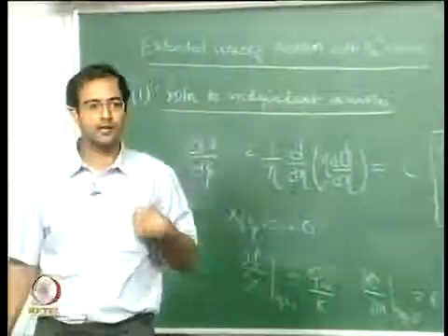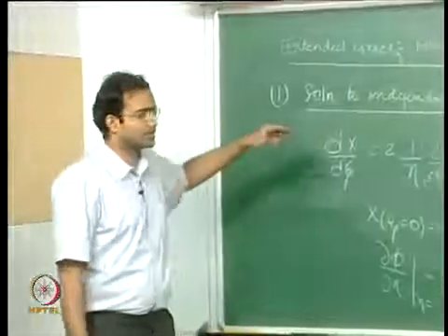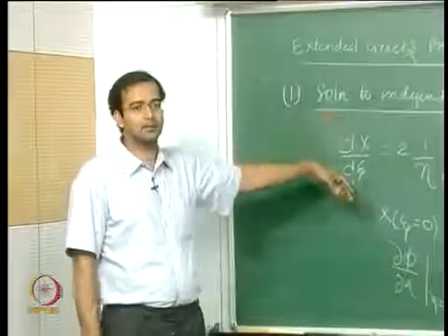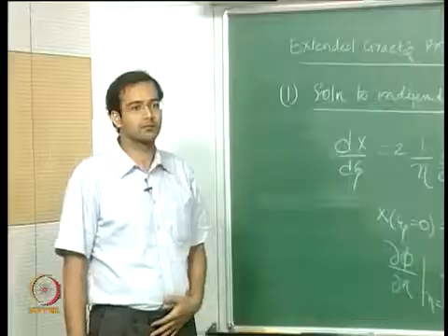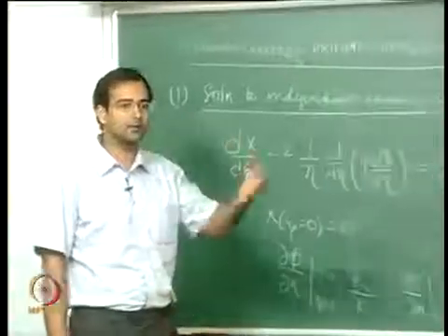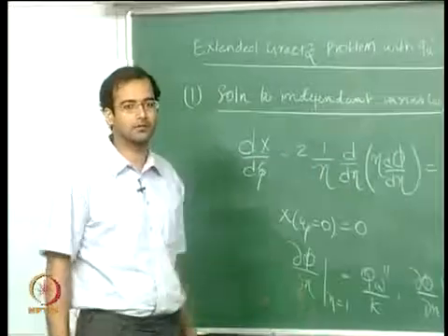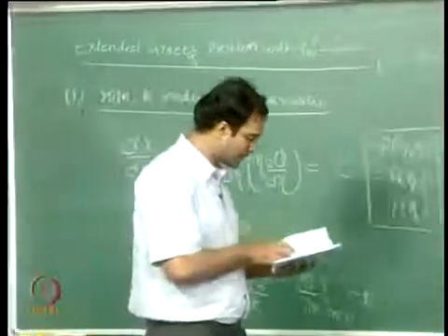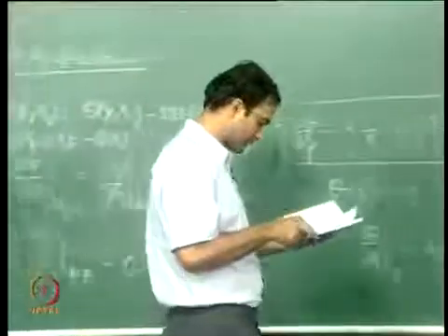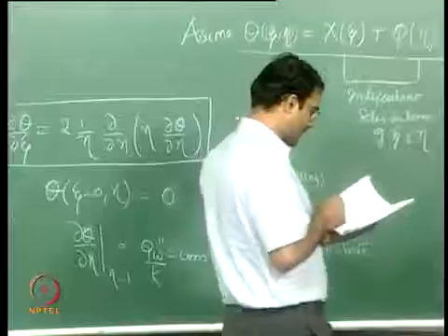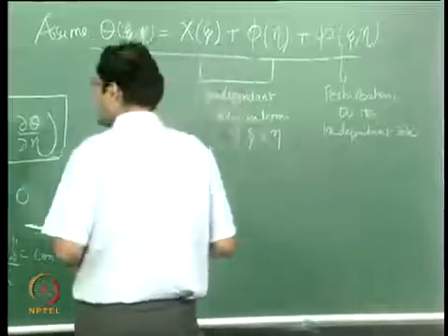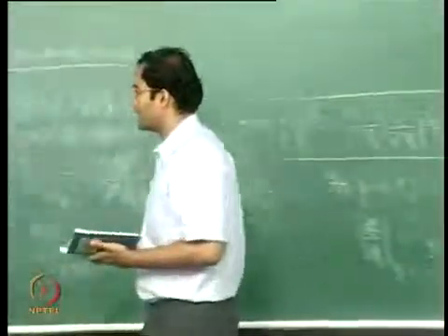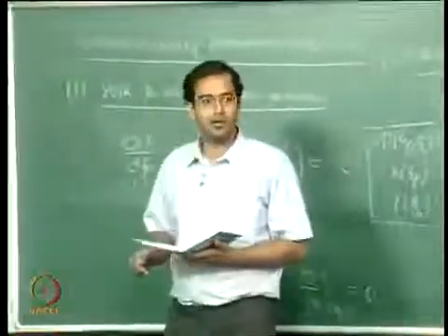Please go through that, and in the assignment I will ask you to do the parallel thing for the duct flow also. Only thing there, you have cosine and sine; here you will be getting them in terms of Bessel functions. The final solution was done by Sellars, and Sellars did both the case of a plug flow as well as the case of a parabolic flow.